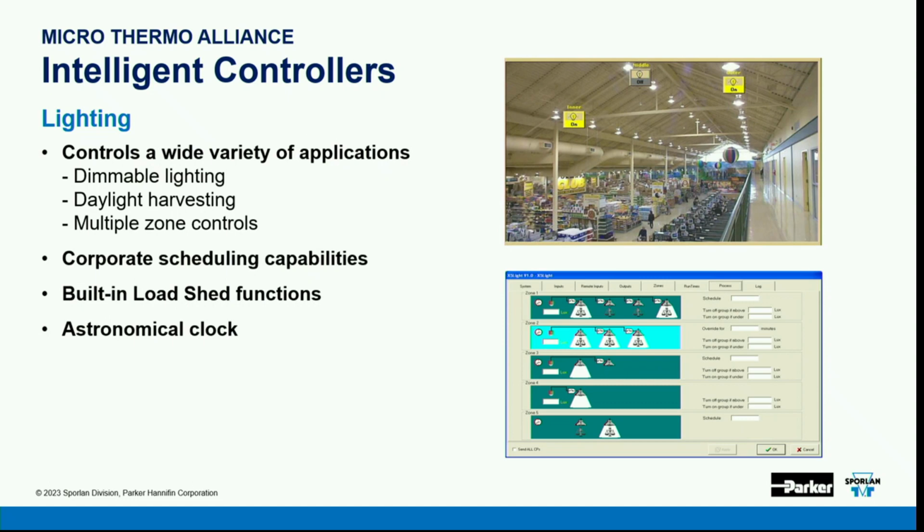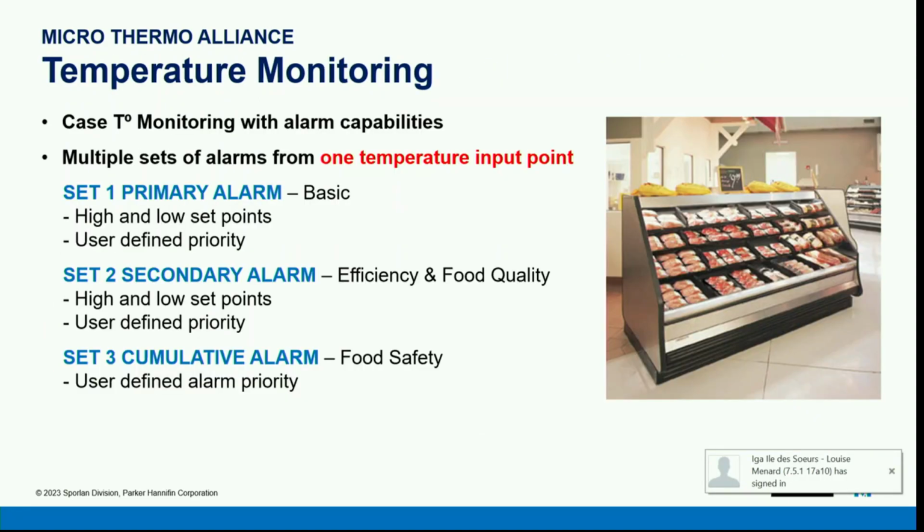Okay, we do put opticals in the store just as a backup in case you get one of those midwinter days, especially in the Northeast where I'm from, and at 3:30, 4 o'clock in the afternoon, heavy overcast, you might need to bump up the lights in the store, maybe even bring the parking lots on. So the optical will work as a backup to the astronomical clock.